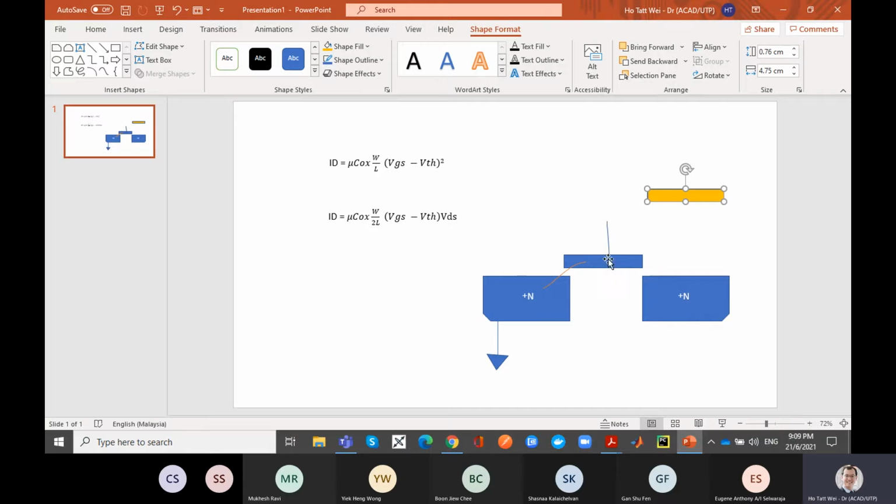But when you apply a voltage here on the gate, what you're doing is basically electrostatically drawing all the electrons down here, drawing them up here to the surface. Essentially the MOSFET is forming a bridge, so that there are free electrons here, even though electrons are the minority carrier here. There are holes here, but electrons are the minority carrier, and they get drawn up here electrostatically because you're applying a voltage here, VGS. So when you apply voltage here, there are electrons here, there is now a conductive path here, so electrons can flow.